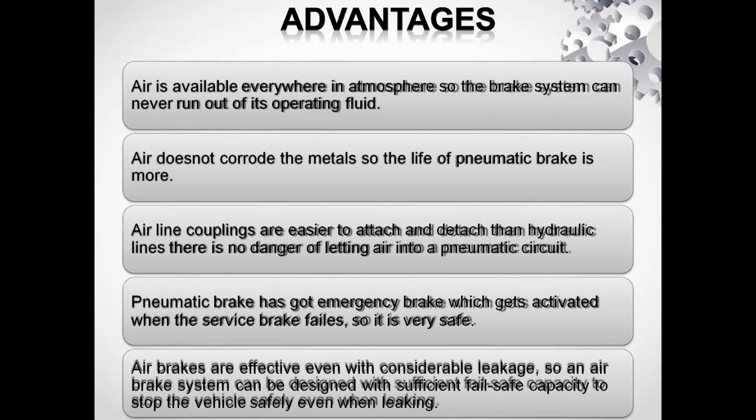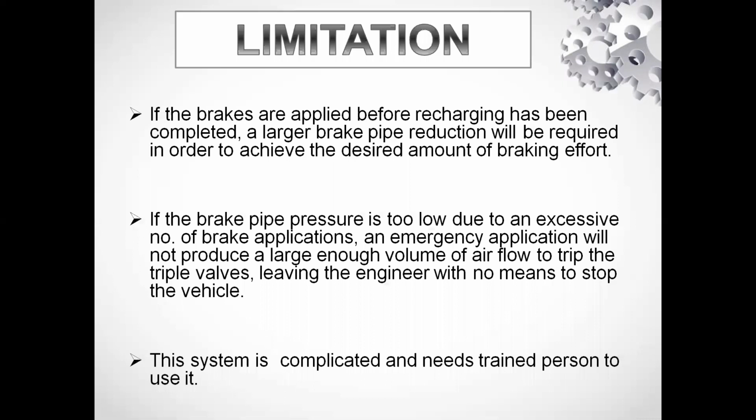Airline couplings are easier to attach and detach than hydraulic lines. There is no danger of leaking air into a pneumatic circuit. And pneumatic brakes have an emergency brake which gets activated when the service brake fails, so it is very safe. These are the different advantages, and now you can see the limitations.